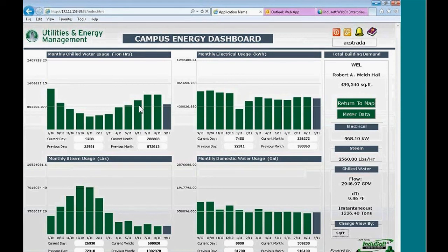And at a glance, if you look at these two areas here, they should have this inverse relationship here. And so at a glance, an energy analyst can look at this and know how this building is performing. You have chilled water data and you have steam usage. So this is how these bar graphs should look.